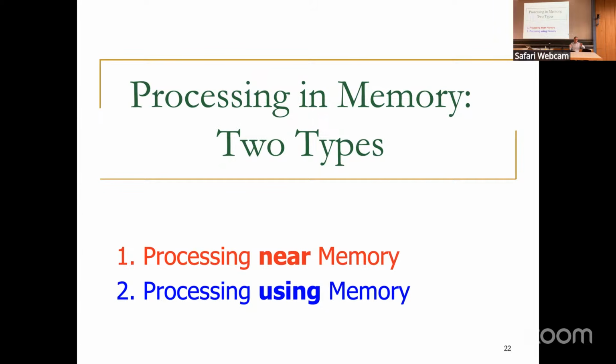There's SRAM, but SRAM is actually compatible with logic, essentially. And that is manufactured using a special logic process. Let me finish this, and then you can ask. And then memory, if you think about most memory today, that is designed in a fundamentally different way. The design of memory, DRAM, flash, and some of the emerging technologies, not all of them, is done completely separately. It's done by different people for sure, but also different tools, different compilers. There's a memory compiler, at least for DRAM, that's very different, and then also different fabrication technologies, right?